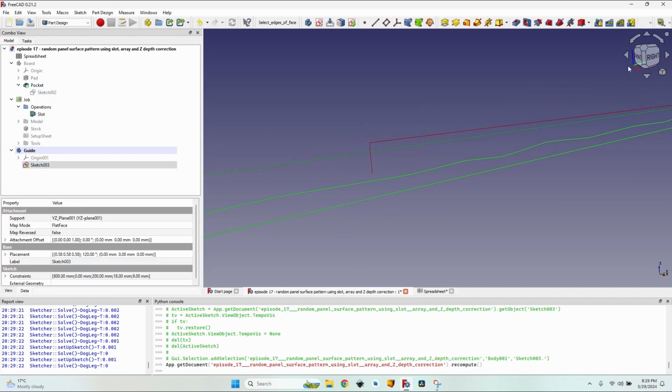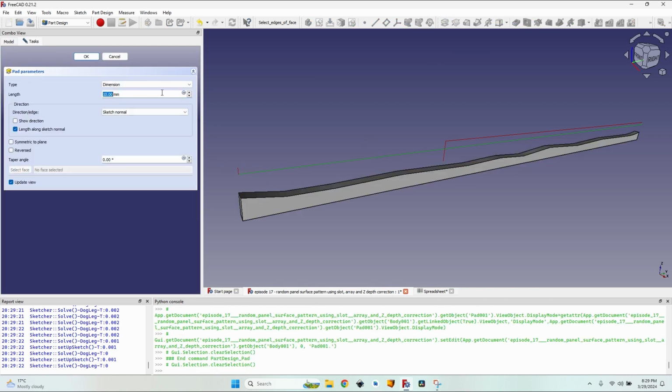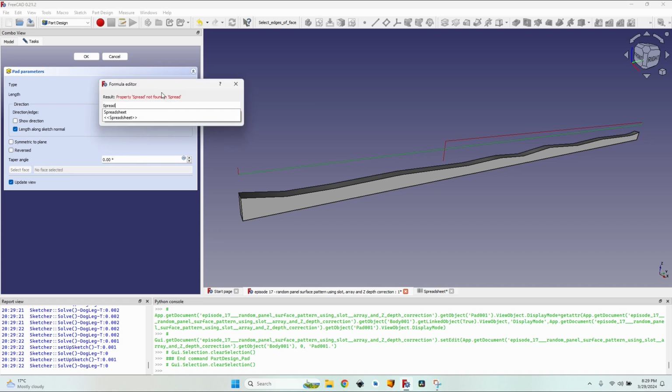You can see, let's look from the right, it's a simple wavy line part of this sketch, and now I can extrude this sketch. Of course you have to make sure that the line that I used as a visual guide is blue, it's construction geometry, otherwise the pad will fail. So I'll create a pad and I'll make the length by pressing equal to the tool diameter.